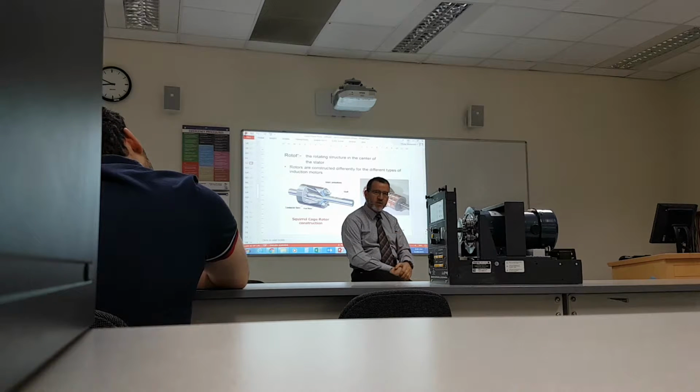If it does pull out of synchronism and does not have a squirrel cage, it will just go close to standstill. If it is equipped with a squirrel cage, at some point below 90%, it begins to fight against itself if it is still excited. So with a synchronous motor, as long as you operate it within range, this is true for any motor.